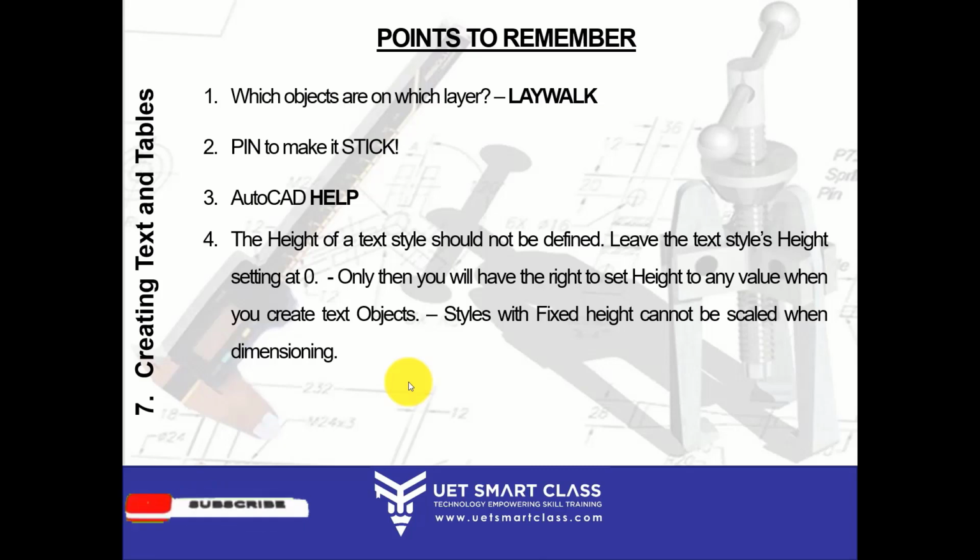Otherwise, it will be a big hassle for you and a weird thing will come out as a print. You will be pulling out your hair. So no need. The simple logic and the simple funda is do not define heights to a text style. Just keep it as 0. It will be very easy for you.